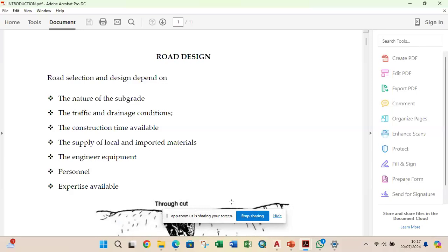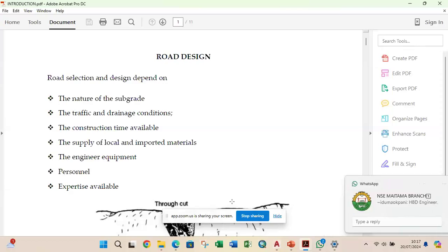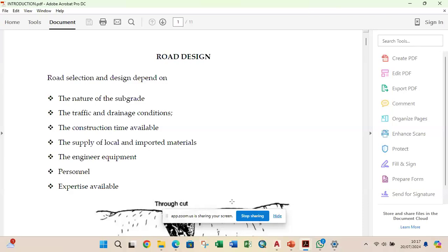The detailed topographical survey is the starting point for any infra work or road work. That is when the surveyor goes with the instrument, be it a differential GPS or a total station, sets out at TBMs, and starts picking out points along the corridor or the environment you're working on. After the surveyor is done, you give those points to the engineer.